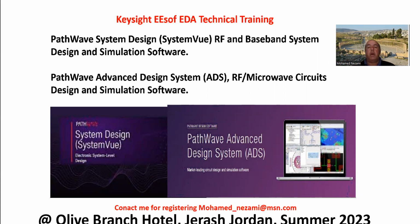And then beyond that, we have another training, which I did not include in here, where you go into Cadence and you use Allegro and OrCAD to do schematic capture and PCB layout. That's where you take the artwork that comes from either HFSS or the Pathwave ADS, the pieces that you EM'd and designed based on EM that are sensitive to layout, and you take it in there.